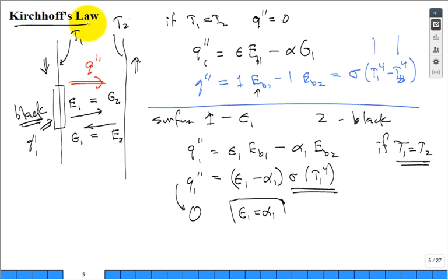If you ask somebody to write down Kirchhoff's law, they'd say, well, for a surface, the emissivity of the surface is equal to the absorptivity of the surface. And that probably I would accept. I wouldn't quibble with them a little bit. But you know about the wavelength characteristic of light? It's really at any particular wavelength. The monochromatic emissivity is equal to the monochromatic absorptivity. If they said something like that, I'd give them a double thumbs up and say, hey, you're pretty smart.